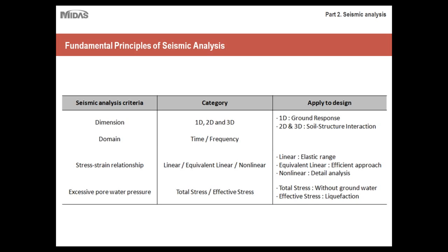When soil is undrained and seismic loading is applied to it, that soil can actually behave as a liquid in a phenomenon called liquefaction. We won't be going into much detail about liquefaction, because that's a deeper concept that would require its own presentation. But keep in mind that when you have undrained soil conditions and seismic loading is applied, that creates a very dangerous and unpredictable environment for your structure. For now, we'll keep it simple and focus mainly on drained analysis. The analysis procedures that we'll discuss will assume that the soil is drained, so without groundwater.